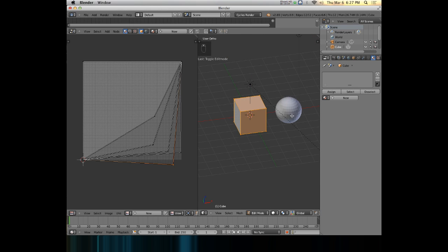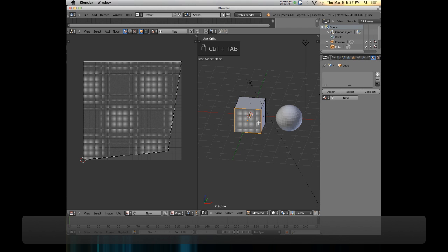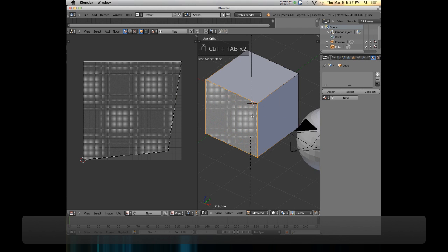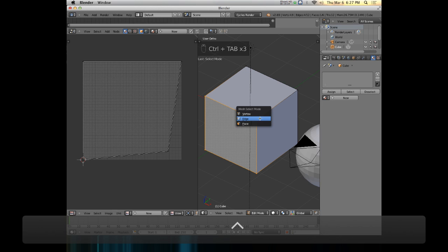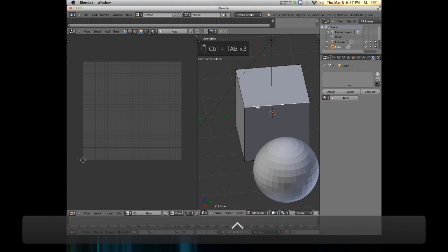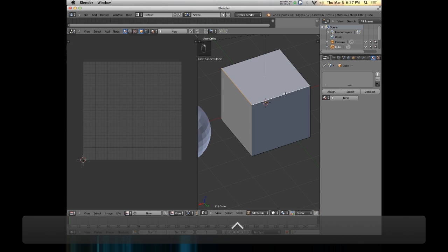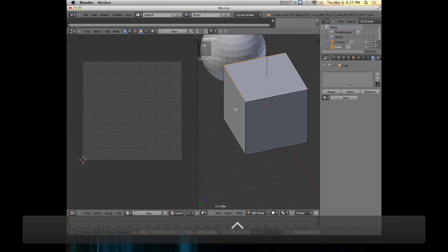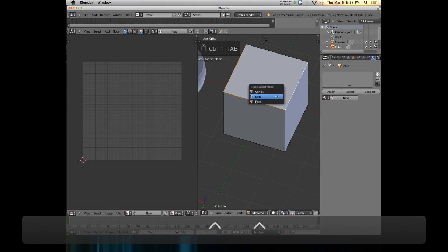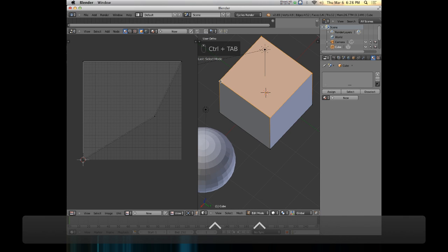So I'm going to first choose what my front face is, and for that I'll just choose this one that is actually facing front, this one right here. And I'm going to go into edge select mode, and I'm just going to start selecting the seams that I want. So I will choose these. The reason why I'm doing this in edge select mode is because if I want these 3 edges to be marked as a seam, and I do it in vertex select mode, I can't just select these 3 edges.